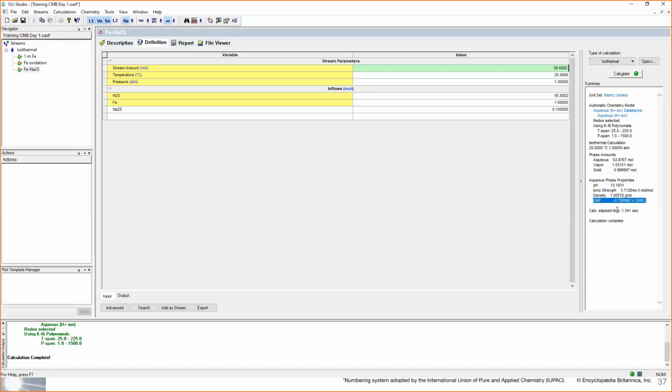The OCP that we will cover in our polarization curves is the open circuit potential. So that is the potential of the metal that you are studying, let's say an alloy, say 316 stainless steel. When you add a metal into your bulk solution, that metal is going to reach an open circuit potential or a rest potential, okay?